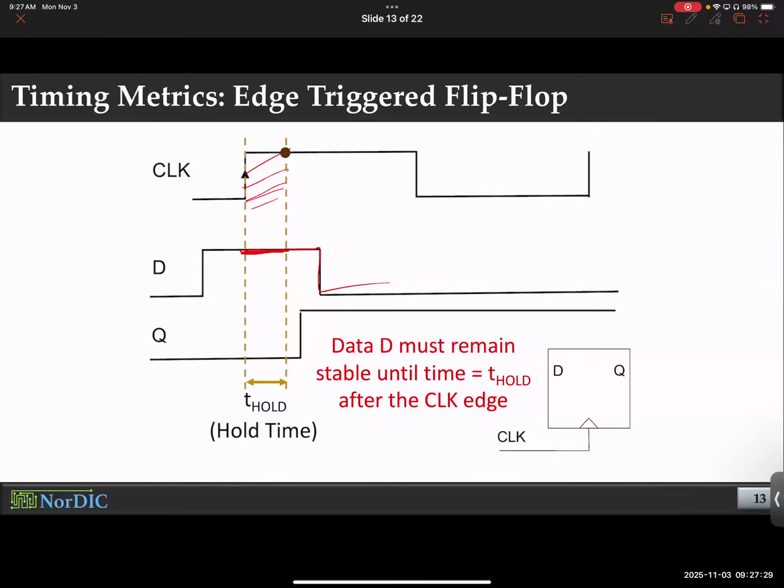That is capacitors, essentially. Remember, every circuit at some point, when you take 433, honestly, I keep mentioning that because only then you start looking at the nitty-gritty details of the circuits. There is a separate lecture on parasitics, essentially. Parasitics stands for capacitors, inductors, something that is more like a residual component of the circuit. You don't connect capacitors in a digital logic. They come for free with the MOSFETs, with the transistors you use. And when you drive inputs, you are essentially charging up capacitors. When you drive output, you are also charging up or charging down capacitors.